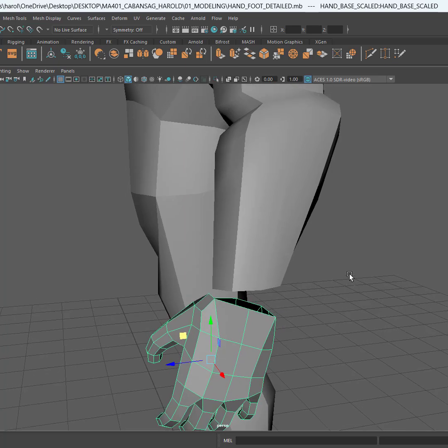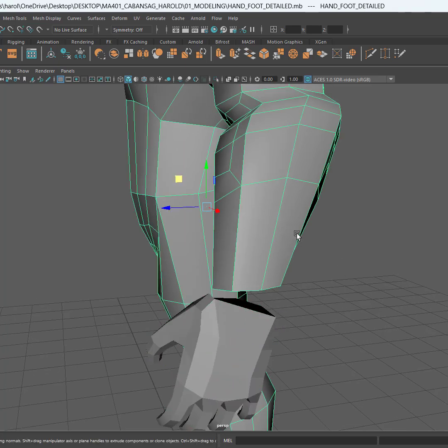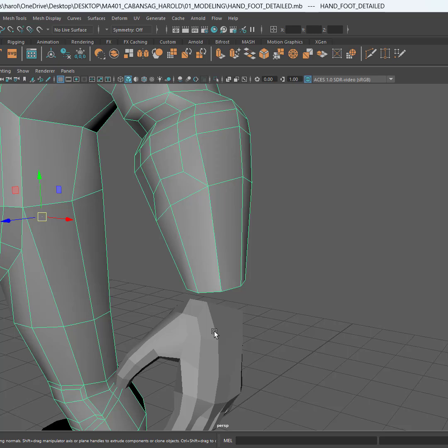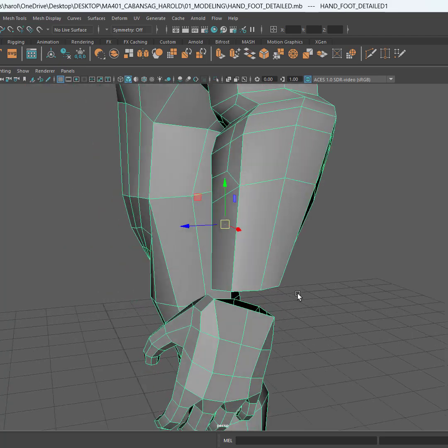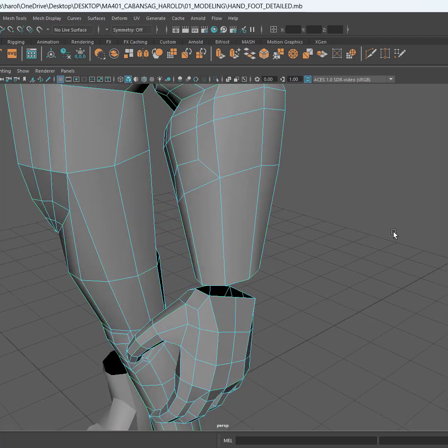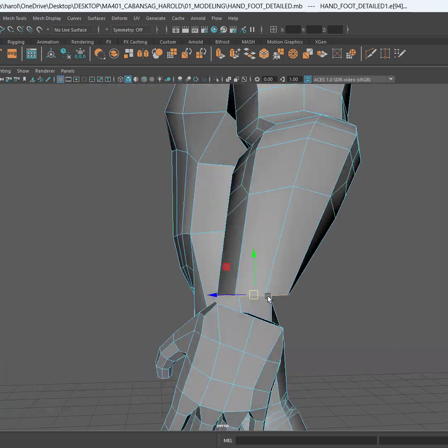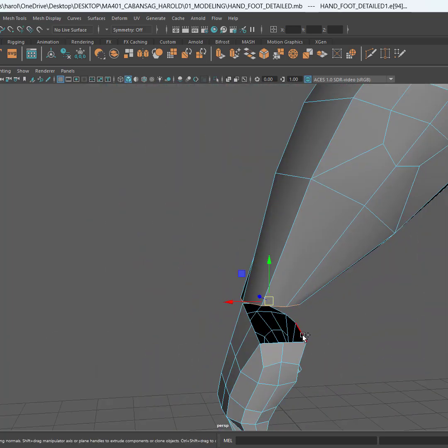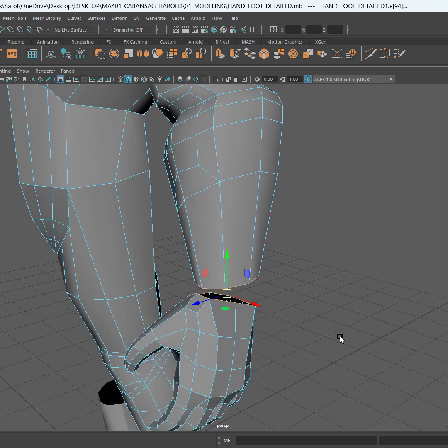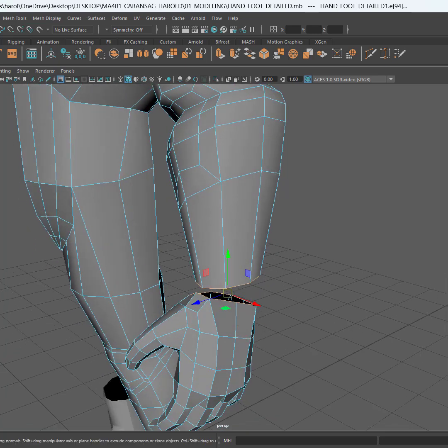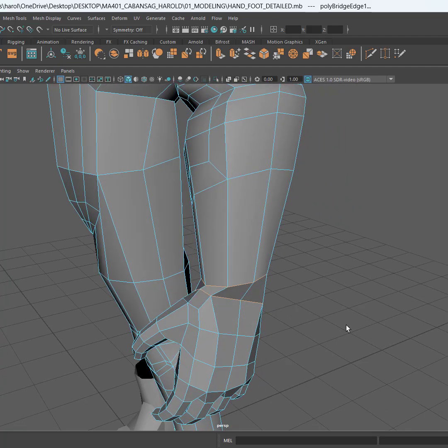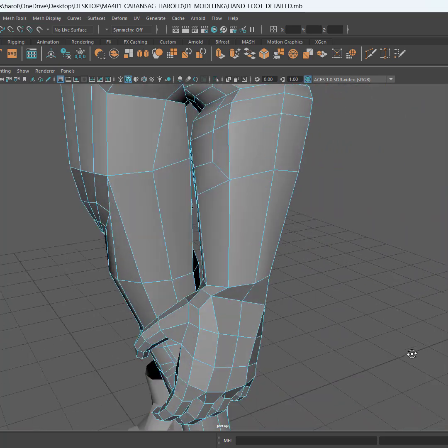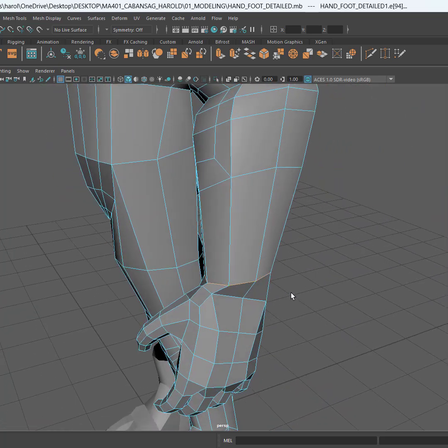So what I'll do next is as simple as selecting these and this, do a combine. After I have combined them, I'll just go to my edges, double click this edge, and I can now double click this edge here, and then now I can just do a simple bridge. Q. Now with that distortion on, I can double click and control backspace to remove the vertices there.